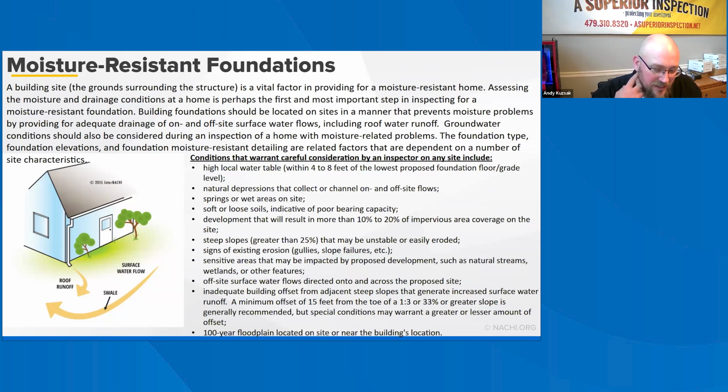So in that instance that I was discussing, one house only had water intrusion into the home. The water got high enough that it came into the home. All the other 3 or 4 houses, the yard was just affected. And then obviously over time, the foundation would be affected if they didn't do something about the drainage. Model building standards typically require a minimum of 6 inches of fall in ground level over a distance of 10 feet from the perimeter of the building.